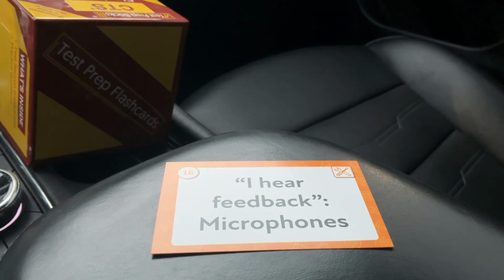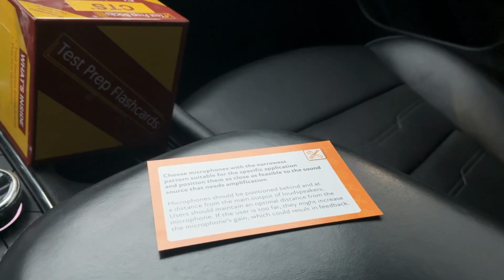I hear feedback. Microphones. Choose microphones with the narrowest pattern suitable for the specific application and position them as close as feasible to the sound source that needs amplification. Microphones should be positioned behind and at a distance from the main output of loudspeakers. Users should maintain an optimal distance from the microphone. If the user is too far, they might increase the microphone's gain, which could result in feedback.